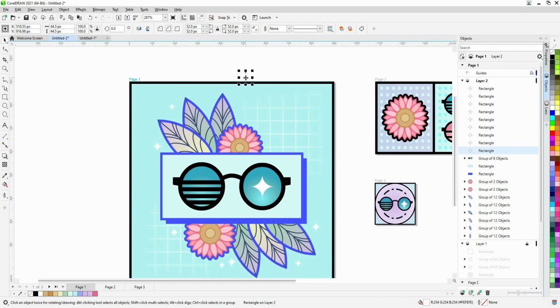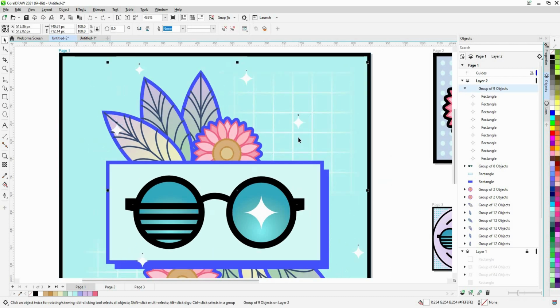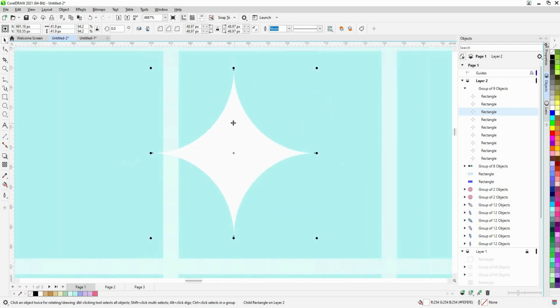Now if I have a group and I want to select an object within that group, I'll just give it undo and get this group back here. Say this is a group, and it's simply a matter of holding Control and I can select that object by clicking on that element. What you'll notice is if I do Shift F2, you can see that the sizing handles are round dots rather than square elements. This is an indication that the object I selected is within the group.